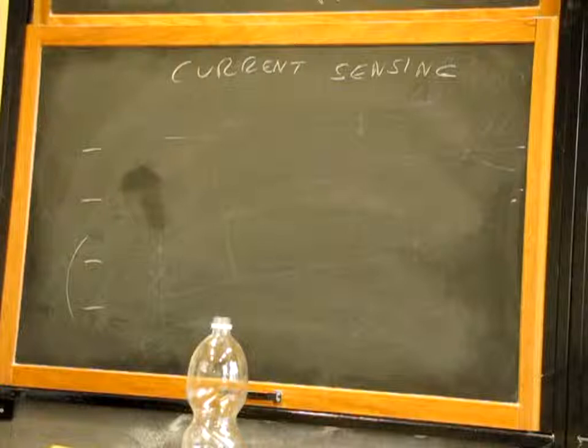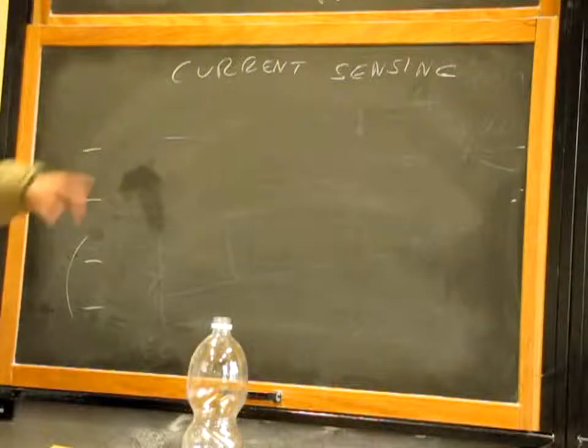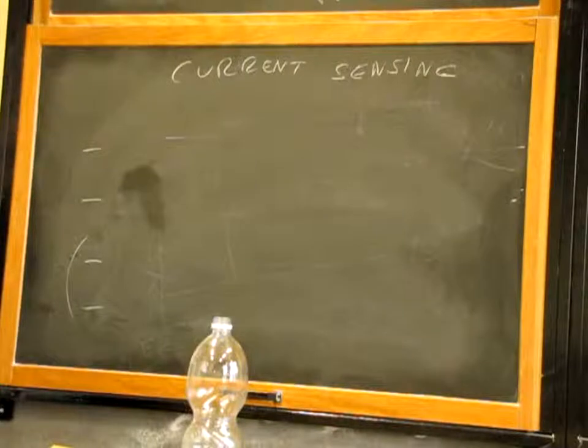We need the current measured on those sections that we discussed earlier to be sent to the comparator, to see when we reach the maximum inductor current, when we have to open the switch.